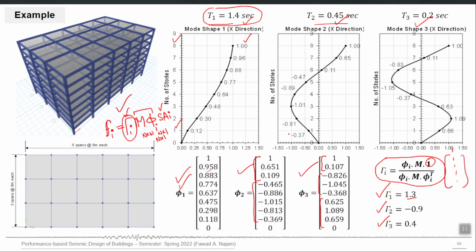Anyways, you have to apply the response spectrum in positive x as well as in negative x as part of the load combination. Whenever there is an earthquake loading, it is not only unidirectional, it is always reversed, right. So, these plus sign forces will become minus and minus will become plus, but when you change the direction of the whole loading case, then it will be reversed again. So, practically there is no effect on the magnitude of the response, right.